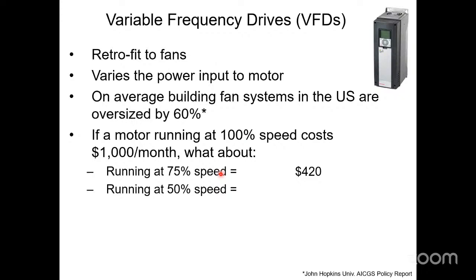Most people would think it would cost 75. Oh, I reduced it 25%. Give me my 25% energy savings. But it doesn't have a linear relationship. It varies as a function of the cube. So the savings is actually pretty substantial. If you can ramp the fan down a little bit, you can save a bunch of energy.